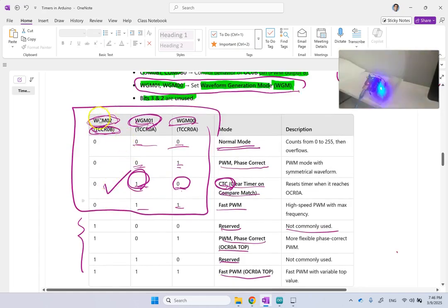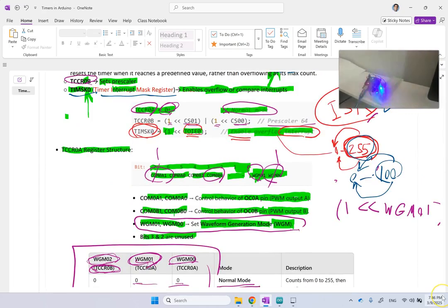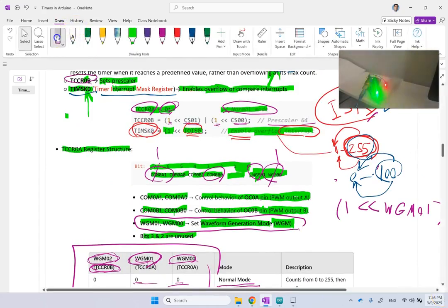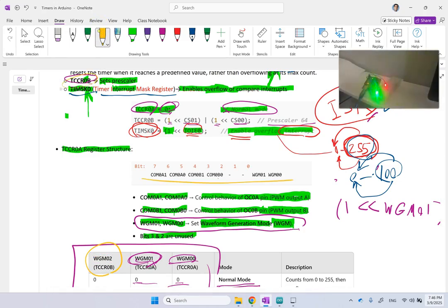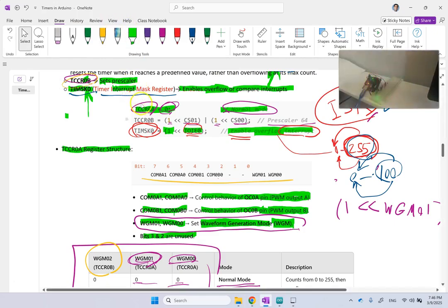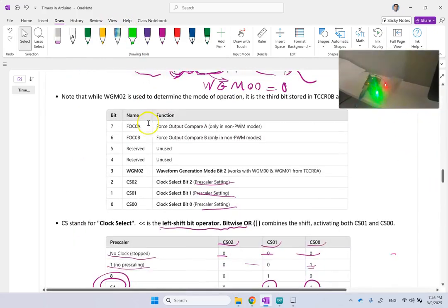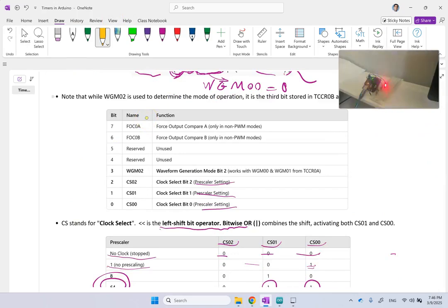The question is, where is that bit WGM02? Because if you look at the timer 1, it's not in timer 1. Look at the timer 1, there is no WGM02 in it. This guy is not in this list. Where is it? As I said, it's in the TCCR0B, and that is what you can see here. This is the structure for TCCR0B.